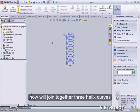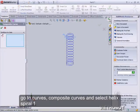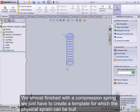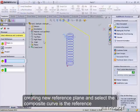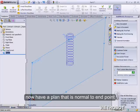Now we'll join together our 3 helix curves. Go to Curves, Composite Curves, and select Helix Spiral 1, 2, and 3 as the entities in our design tree, and click OK. We're almost finished with our compression spring. We just have to create a template from which the physical spring can be built. To do so, select the bottom endpoint of our sketch, create a new reference plane, and select the composite curve as the reference. Now we have a plane that is normal to our endpoint.